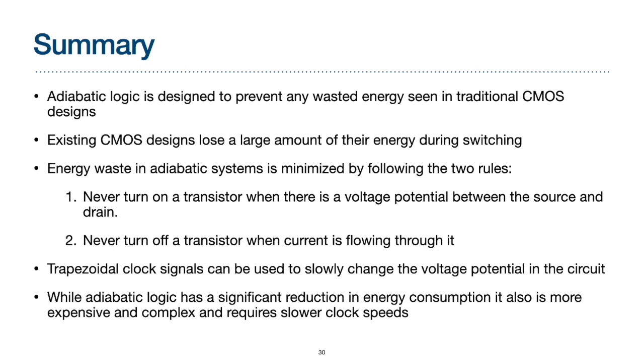The last point to take away from this presentation is that while adiabatic logic has a significant reduction in energy consumption in some situations, it also tends to be a more expensive solution to implement and more complex, as well as requiring, in some situations, slower clock speeds, which may reduce performance. However, in situations where performance is less important than energy consumption, you may find that adiabatic logic is the better solution to your problem.